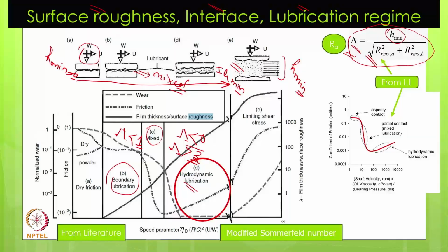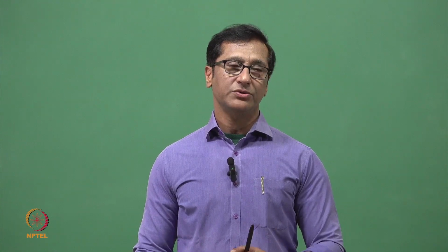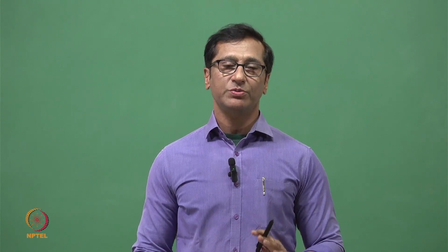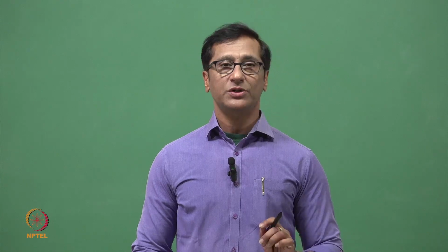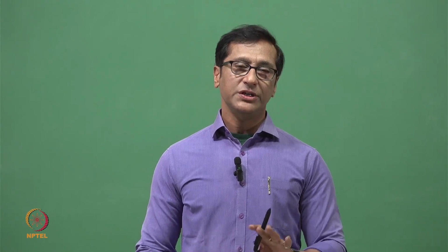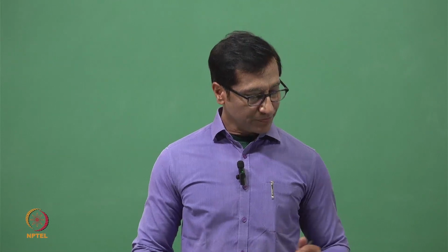So we can go ahead with this relation initially for understanding purposes, but for detailing purposes this relation may not be enough, because we need to account for whatever interaction happens. If it is hydrodynamic, we need to account for it. If it is elastohydrodynamic, we need to account for it. If it is really asperities, we need to account for them. If some sort of boundary layer is getting formed on the asperities, we need to account for that. So we need to account for all those aspects.